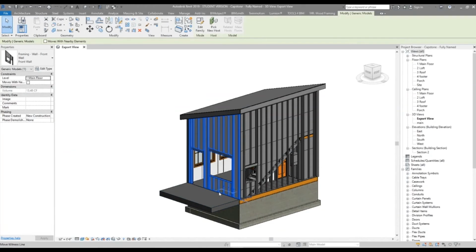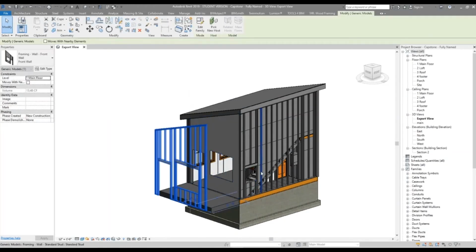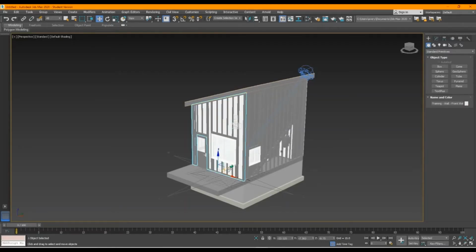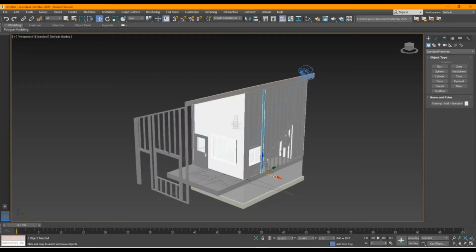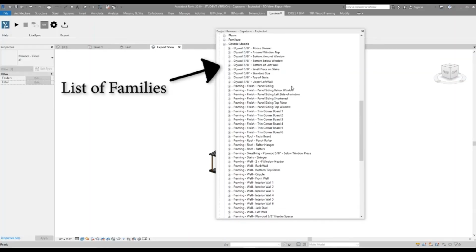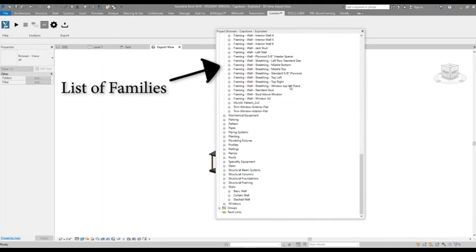At this point, how the models are created comes into play. In Revit, anything that is in a family will import as one object in other softwares down the line. So in order to work with this, for the fully explodable wall located on the right side, all of the individual pieces, such as wall studs, sheets of plywood for sheathing, single pieces of siding, etc., are individual families. Whereas elsewhere, for example, the wall framing is one family and therefore one object in 3ds Max and Unreal Engine.